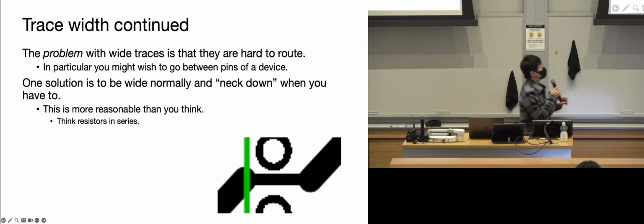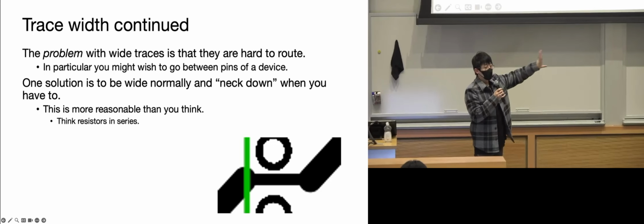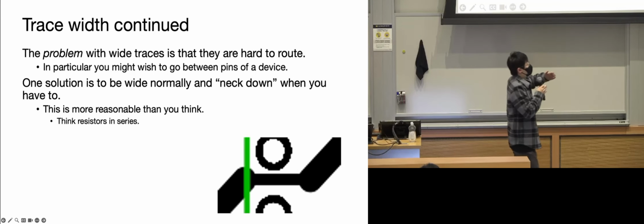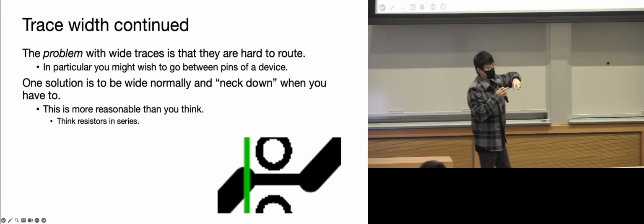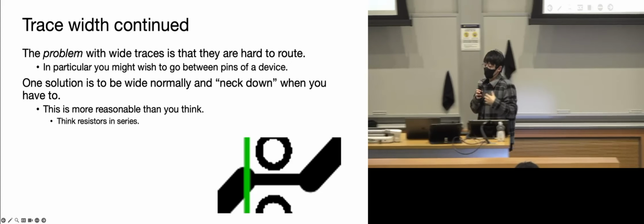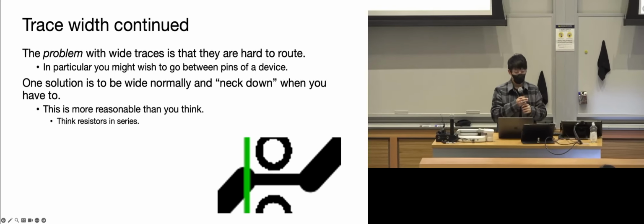If there are cases where a wire needs to go through 2 holes or between other pads that are very close to each other, it's also not unheard of to have those small parts be a little bit thinner than the rest. If it's not a very high frequency signal, it's usually okay.